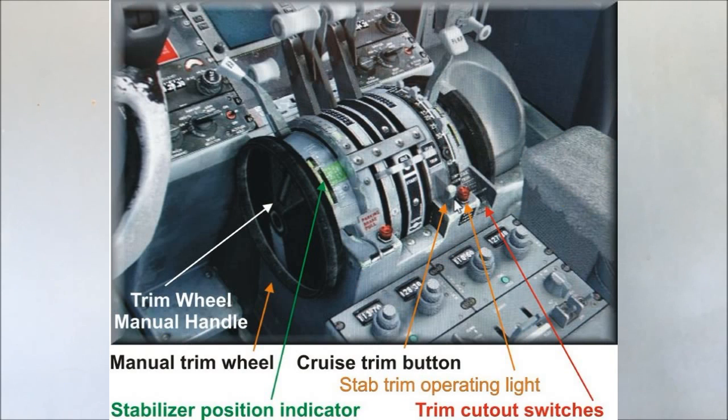A controllable trim tab is adjusted by mechanical means from the cockpit, usually with an indication of its position being displayed to the pilot. Most aircraft have trim on the pitch control, and more aircraft have trim on the 3 axes. Pilot control is by lever, wheel, switch, and others, by mechanical, electrical, or hydraulic actuation.